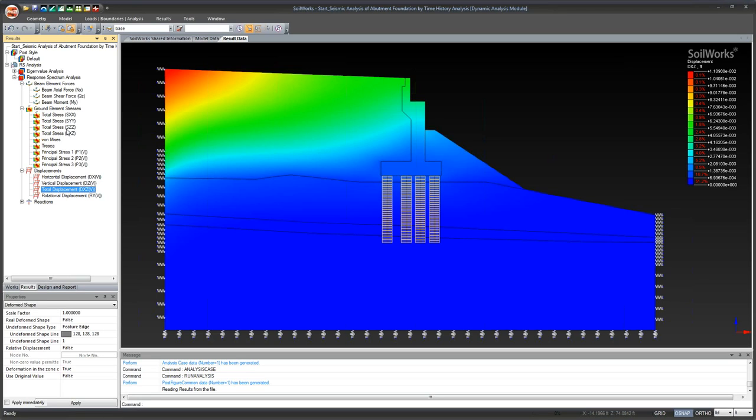Typically what you'd focus on is just the response of your support structures as well as your vertical displacements. So this is all you really need for response spectrum analysis. And as I just showed you, it's very simple, very straightforward. If you're familiar with response spectrum analysis, you should be able to start using the program immediately to start doing your analysis. And then also your eigenvalue analysis.